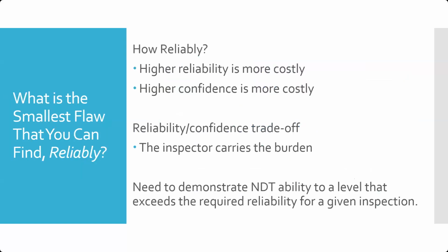So here we've moved the question to what is the smallest flaw that you can find reliably. We need to know how reliably. But reliability comes at a cost. Higher reliability is more expensive, as is higher confidence, which says that we will find a flaw every single time. So there's a reliability and confidence trade-off with a given cost. And so the inspector ultimately carries the burden of this.